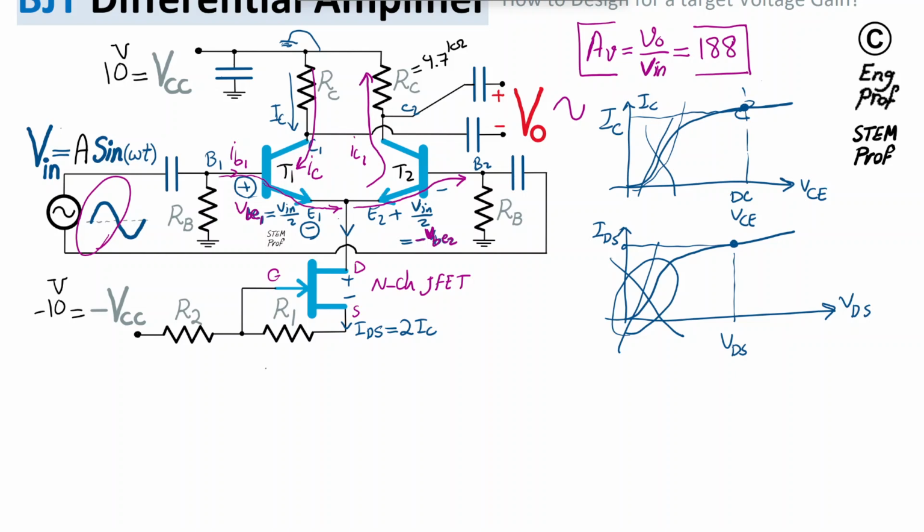Let's refer to it as IC1, good enough, going up. So we have a loop like this. And because of these AC currents passing through these two transistors, it's as if we have an AC voltage drop like this across the RC. So as if we have plus minus AC voltage across RC, and then we have a matching exact drop plus minus across this RC.